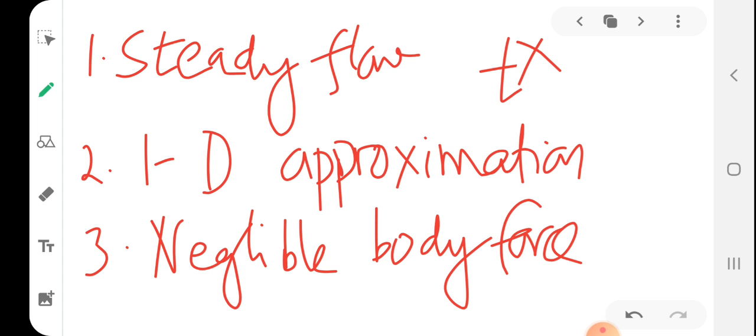So have you understood? The body forces are those forces associated with the mass of the flowing fluid. Since we are deriving equations based on a small control volume, at any instant it has very small mass of fluid. The force due to this mass of fluid may be very small. It can be reasonably neglected. By using this kind of approximation, it makes only very insignificant deviation from reality. So this can be applied.